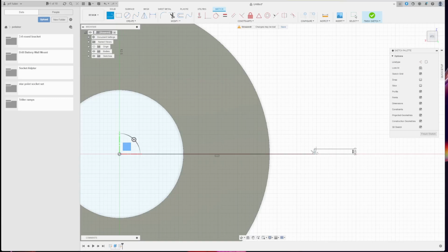And I can go back to my line tool now, and I can draw all the way through it down, making sure that I enter 0.05 and putting inches in, which will come over my splitting line or my construction line that I put in there very fast. And I'm just drawing a line all the way out, hitting escape, and then I'm just going to put L again for line, and I'm going to draw a line down past this and press escape again.